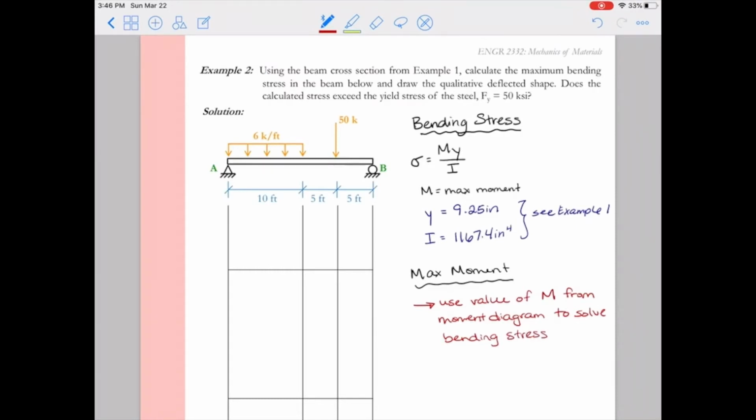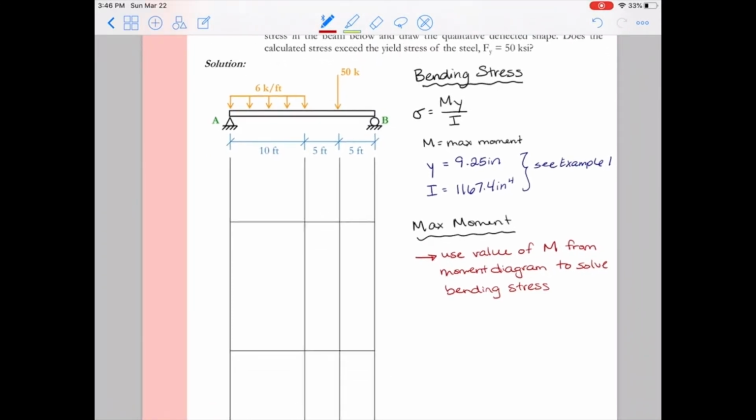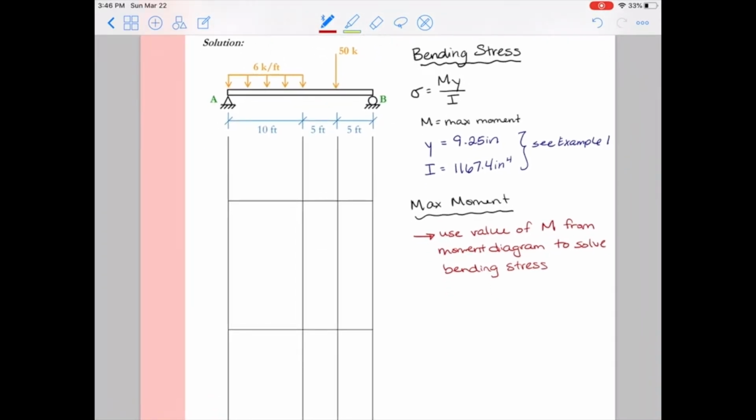All right, so how do we get started on this moment diagram? Well, like all good things, we start with equilibrium. So let's draw our free body diagram, with forces AY, BY, and AX. And then I'm going to do my equilibrium equations using that free body diagram. So free body diagrams start us off, and then we do equilibrium equations, the good old one-two punch. It's going to get these beams whipped into shape.